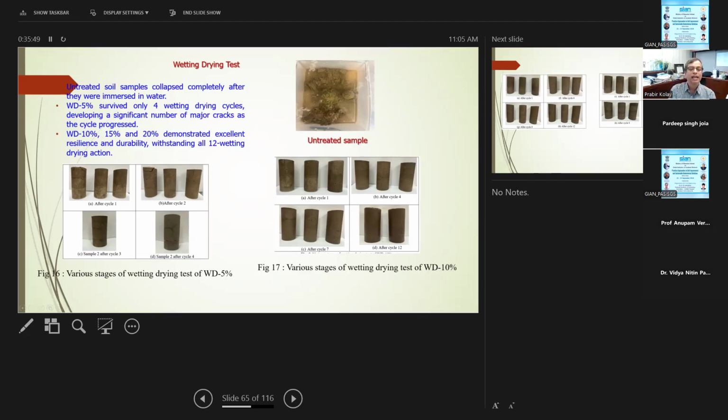These are the samples you prepared, and I'm not going to explain how to do that. Most of the time there is a standard procedure, ASTM. You prepare the sample, insert it into the water, keep it for a certain time, and then take it out. Then you dry it, brush it using a wire brush, and see how much is the loss. From there, you can calculate the mass loss, the volume change, all these things.